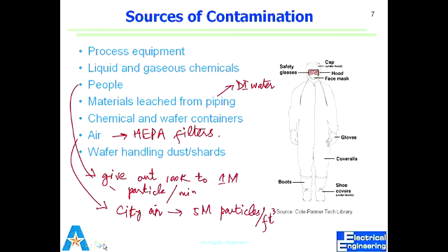Chemical and wafer containers, so the containers that we use to move the wafer around. In your case, it would be your tweezers, because you'll be holding your wafer with tweezers. If your tweezers is not clean, it's going to screw up your wafer. Now think about it. You have to be very careful. I would say, use common sense. So if I'm using this tweezer to hold my wafer and I put the wafer in a holder, right? Now what do I do with the tweezer? Can I hold it in my ear? Can I put it on the bare surface table? Can I put it in my pocket?